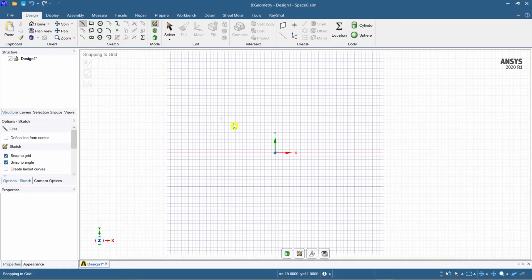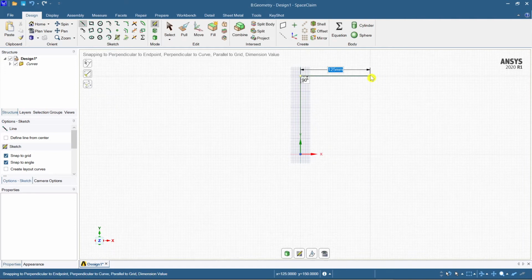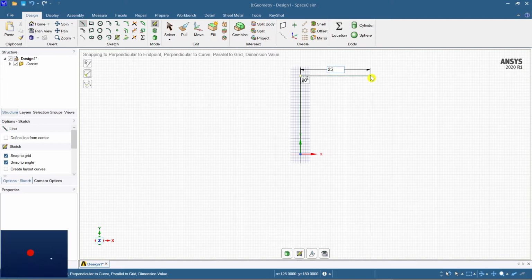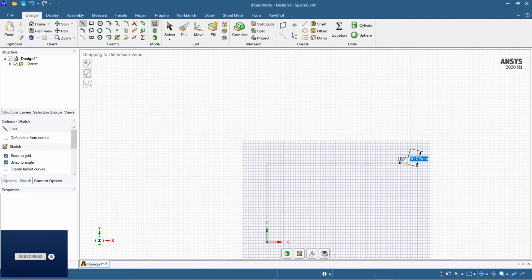Now what I'm going to do initially is start with a tread and a riser. My riser is 150 mm height. Let me consider my tread as 250 mm. So this will continue.